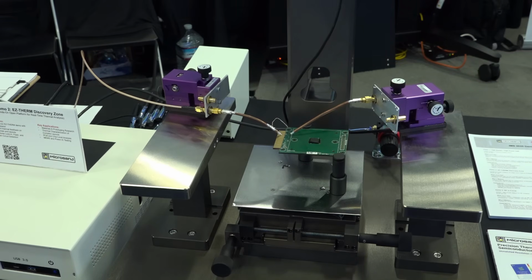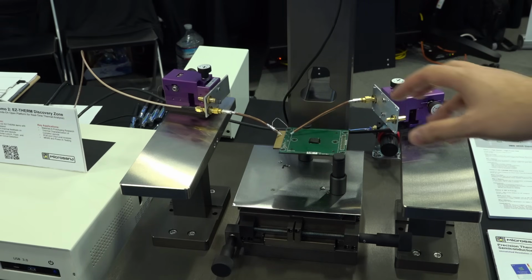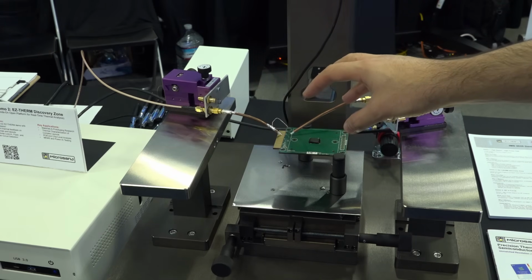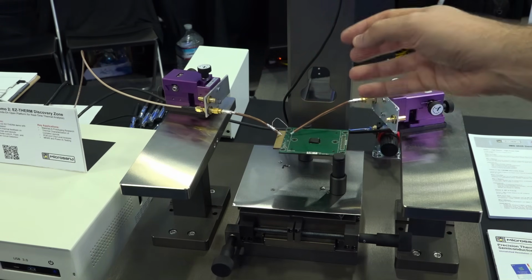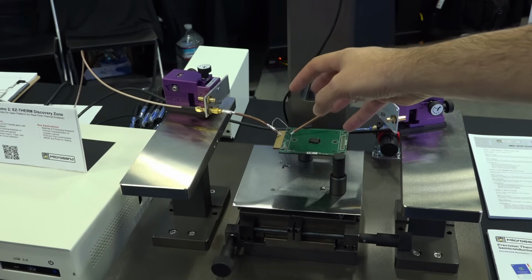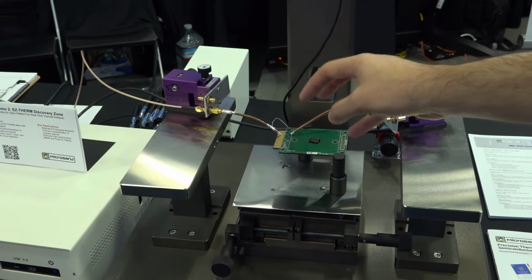So here I am at Microsanj. Now, in the past, I have recorded videos about their thermal reflectivity systems. What they're doing over the years is looking at ways to leverage their thermal management and thermal measurement systems to extract some new ways of looking at circuit flaws and circuit performance. So consider, for example, a circuit like this, fully assembled, and there is a break or a disconnect somewhere in the system. Now, you can excite different traces on this and look at the thermal reaction of those traces.